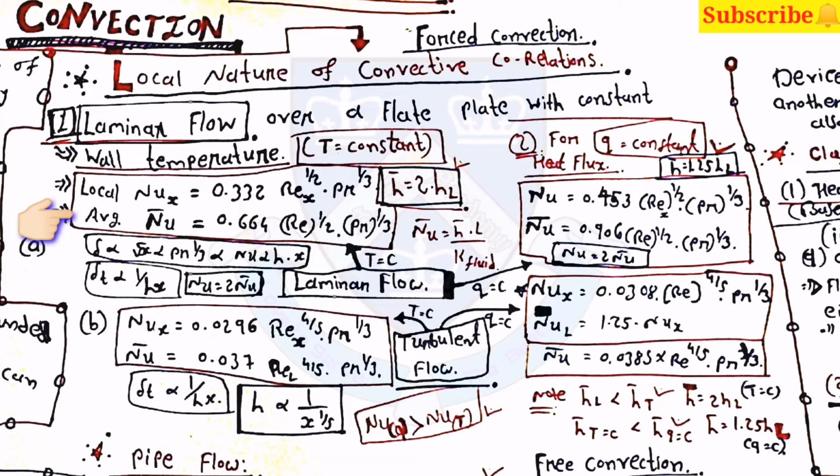In this type the temperature is constant, and in the second type the heat flux is constant. Here the value of Nux is equal to 0.453 into Rex raised to 1 by 2 into Pr raised to 1 by 3, and Nu bar is equal to 0.906 into Re raised to 1 by 2 and Pr raised to 1 by 3. Then similarly for turbulent flow the equations are given.